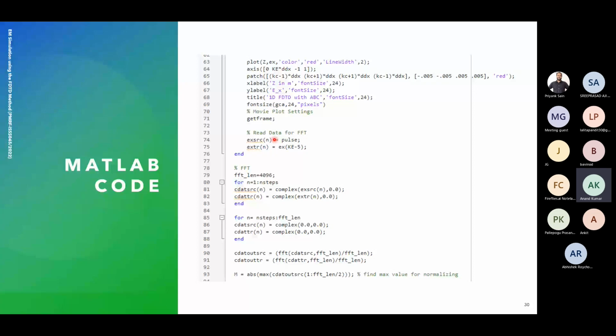Here are the different functions to make the plot window. Before we end the loop, we choose the points where we want to record the data of the field. If we have a wave propagating and we want to see it in the frequency domain with the FFT, we record the values of the wave when it passes through that node.